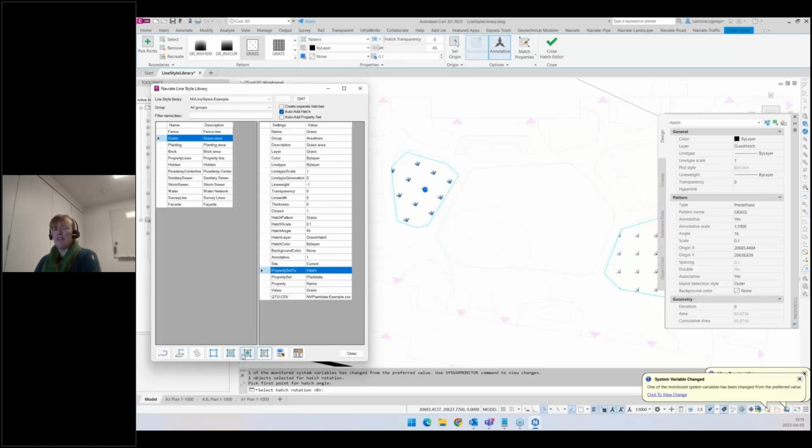We have two different hatch commands down here, select objects or internal points. So it's the two hatch versions that we're used to. But we have a couple of different polyline functionalities here that I wanted to show you as well. 3D polyline, very normal, but we also have M polygon and B poly. And maybe not everyone is aware what these two are.